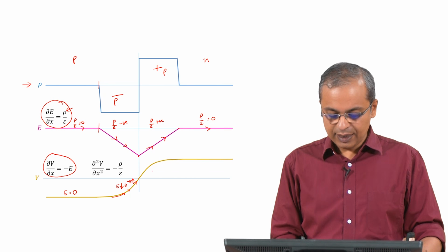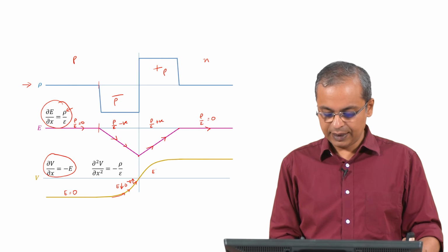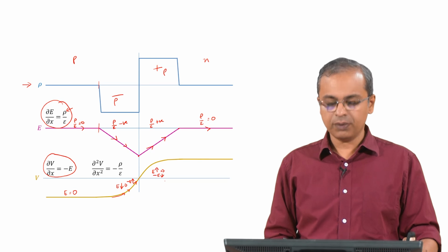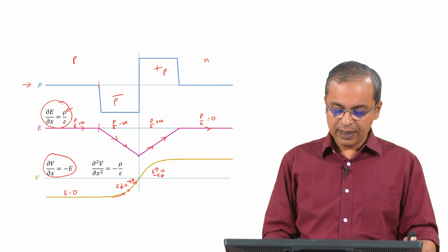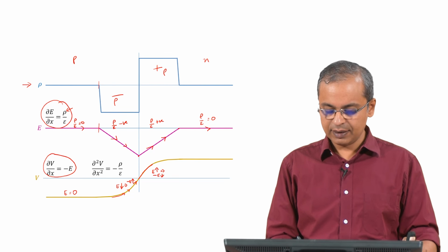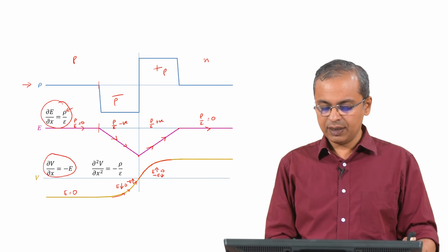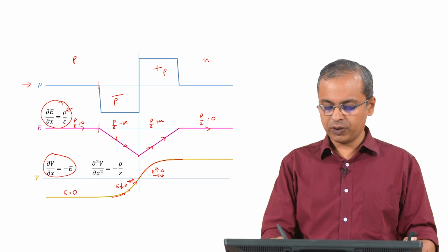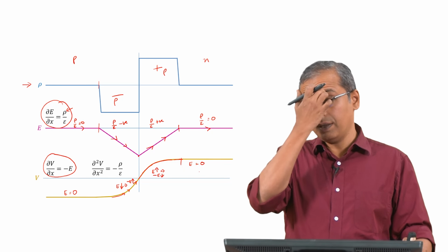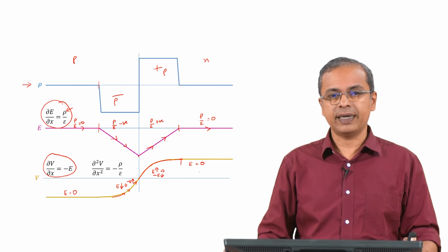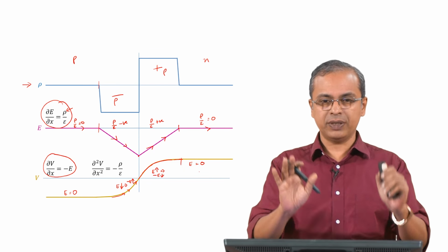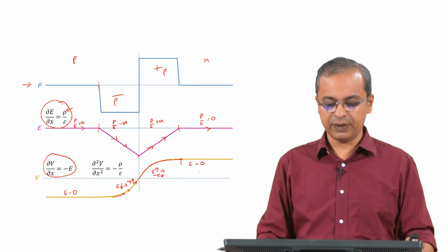You suddenly see here E is basically increasing, which implies minus E is decreasing. Okay. Because minus E is decreasing, the slope, having reached some value, now starts decreasing. It starts decreasing like this, and then once you reach this flat region, corresponding to this point here, E has become 0. Okay. And so, once E is equal to 0, the slope is 0 and you again get a flat line. So, this is the behavior of this junction in its static state, as soon as it has been built or once it is in that kind of stable situation.